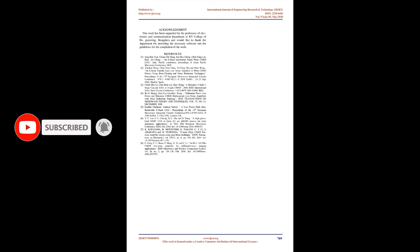VSWR provides information about the standing waves arising due to reflection of electromagnetic waves from the metal contacts. VSWR values ideally should be 1, and in the current design it has a value of 1.0108. The VSWR plot, Fig 5, is as shown below. The results are tabulated and shown in the following table.